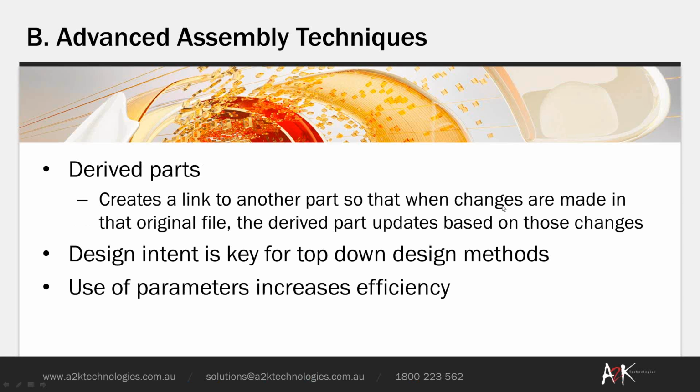Moving on to the next slide. I mentioned derived parts, and all the design techniques we mentioned above have derived parts in them. What a derived part does is it creates a link to another part so that when changes are made in the original file, the derived part updates based on those changes.